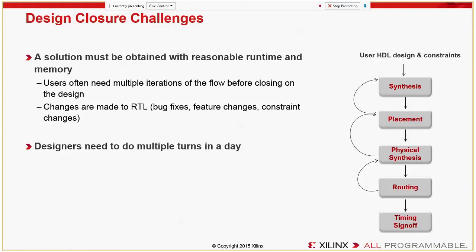So the implementation design closure process is actually, as I mentioned, a very complex one. What's very important to users or designers is that they would like to do multiple turns in a day. Bear in mind that these are designs that typically have hundreds of thousands and in some cases even millions of logic gates. And designers typically would like to do 4 to 6 turns in a day so that you can actually be productive. So this means that EDA tools must obtain a solution of one pass through this flow with reasonable runtime and memory.